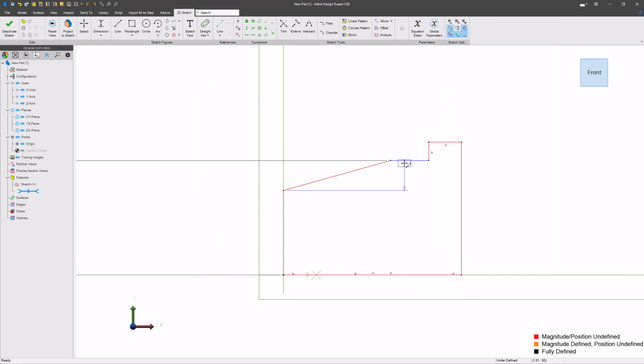And then I care about my taper, of course. Now taper in NPT is given by arctangent of 1/16. And if you look at this, you'll say, well, the arctangent of that angle is actually given between both sides, and we're doing only one side. So once again, we're going to divide that by 2, and that should be the right taper.